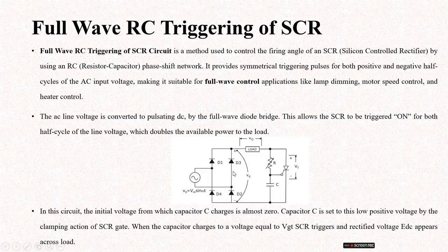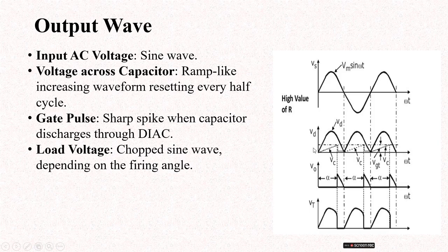To study the effect of the capacitor on triggering of the thyristor, consider the positive half cycle. Observe the waveforms: the diode voltage, output voltage, and thyristor voltage. During the positive half cycle, the capacitor charges with the upper plate positive and the lower plate negative. The capacitor takes time to charge, hence it follows the VDC graph with a small delay.